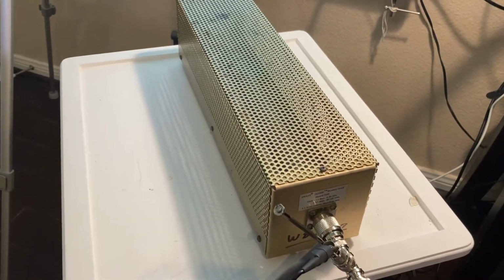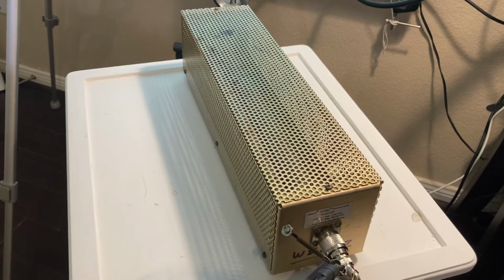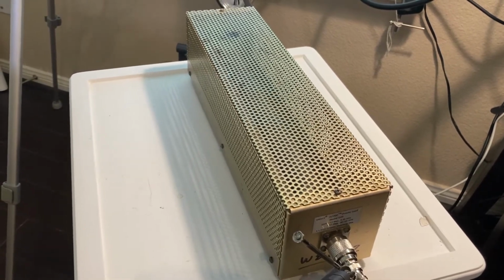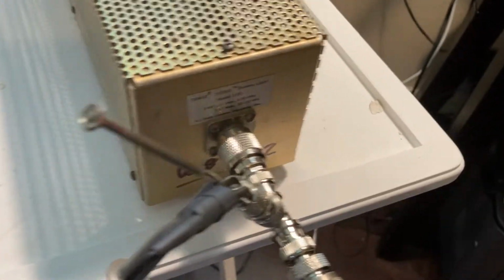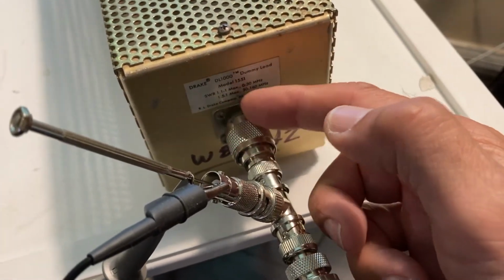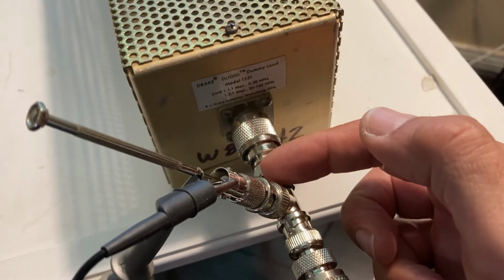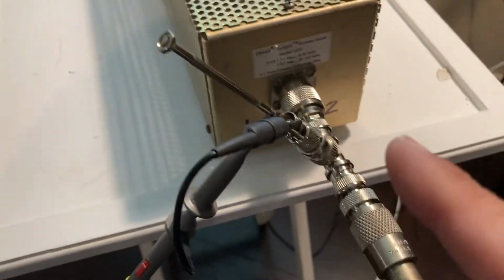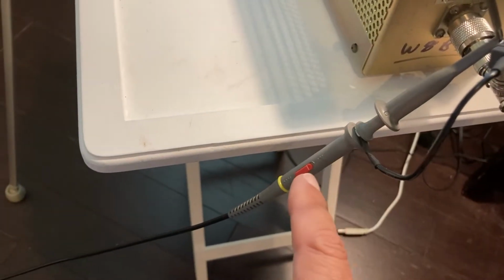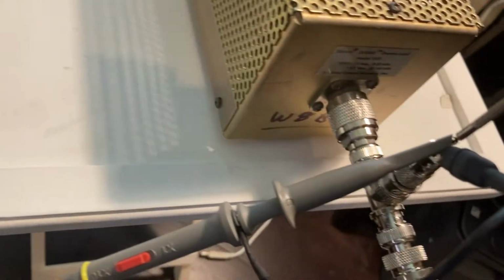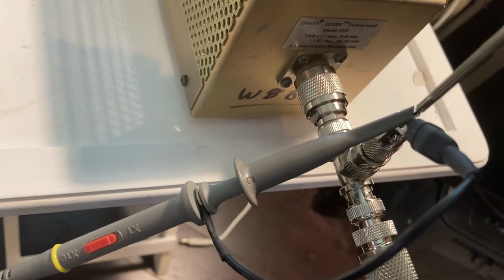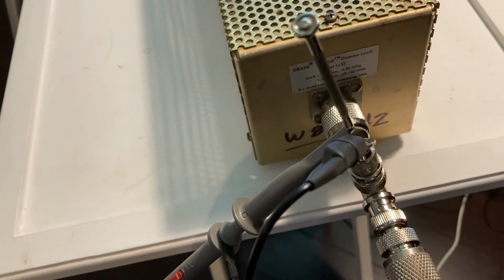So for the powers of up to 20 watts that we expect, maybe 25, 30 at most, we should be okay. Now the setup that I've got over here are some crossovers, because this is PL259, SO239, going to BNC. The reason I've done this is that I want to use the times 10 probe. So I had to set this up so that it goes in there, and the grounding goes right out there on the sheath of the BNC connector.